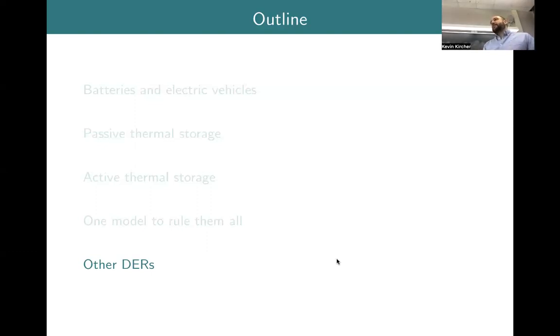Similarly, with the water heater, we have these dissipative losses, heat bleeding out through the insulation in the walls. Well, where's that heat going? It's going to the building. So there'd be coupling between a water heater model and the building model as well. And then even within a building, you could have air and thermal mass, and you'd want to treat both of them as batteries. And naturally, there's some coupling there. So it might make sense to use not two separate one-state models, but a genuine two-state model, like the 2R, 2C thermal circuit that we talked about.